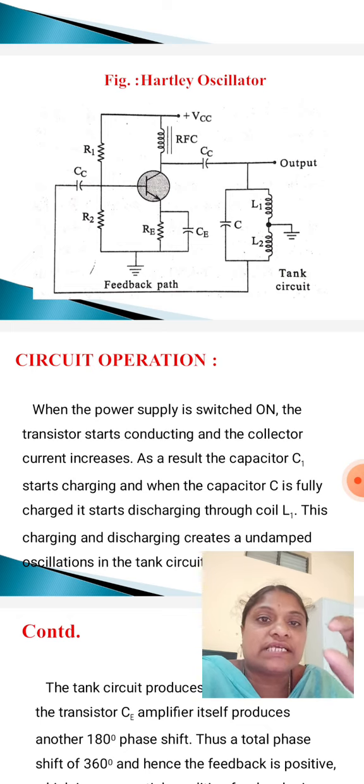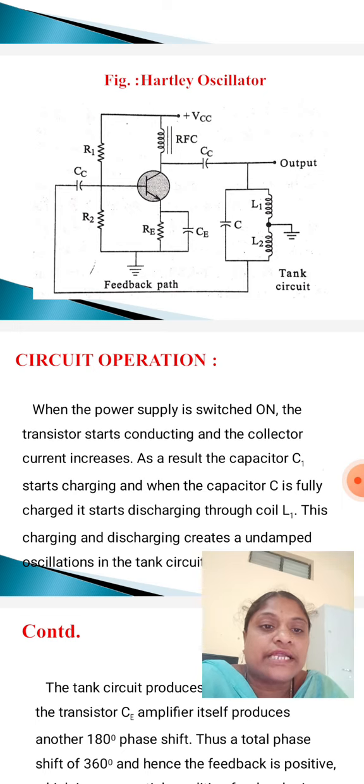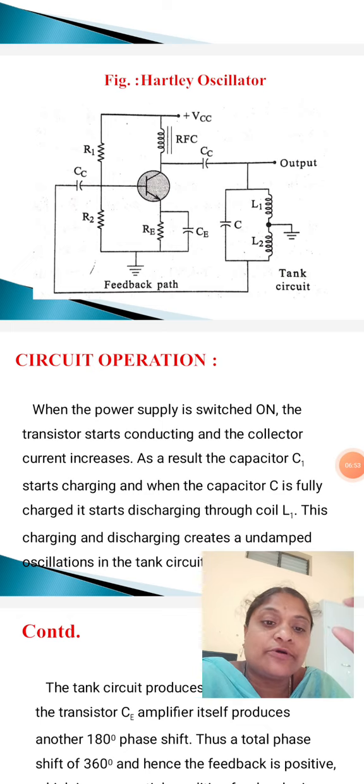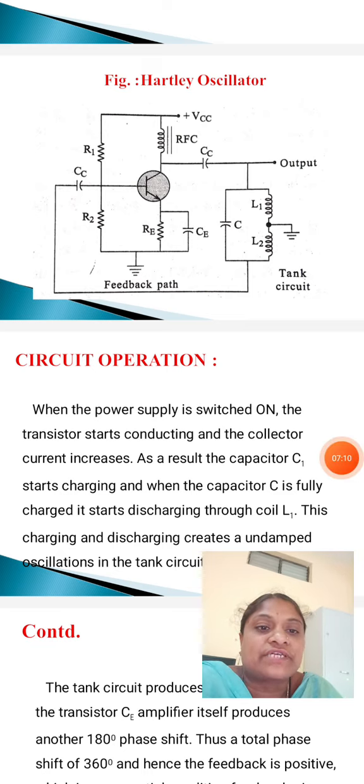I repeat once again the functioning of RFC. RFC is nothing but radio frequency choke. What is the purpose of RFC? RFC permits the flow of DC current but blocks AC current, because of the AC signal on the power lines affecting the output signal.